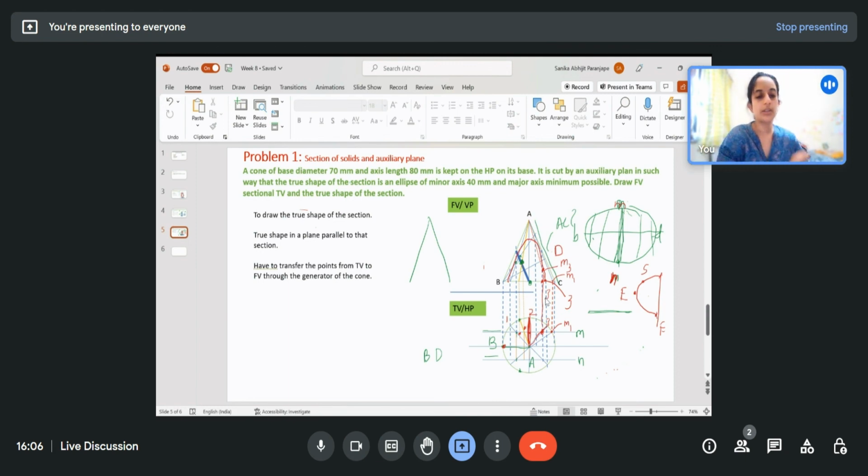So what you do is you imagine that if I had this particular line A2, and I rotate it here to here, then this point will come here. This point I can project it here somewhere, and wherever this will intersect, that will be the vertex. So this point will correspond to this point. So this will not be the correct figure. My hyperbola will come like this, a little shorter in length here. Alright. So that is how you project the point on line A2.